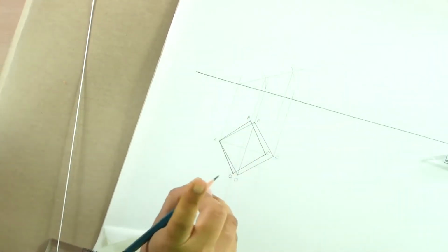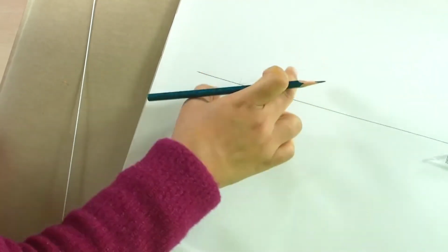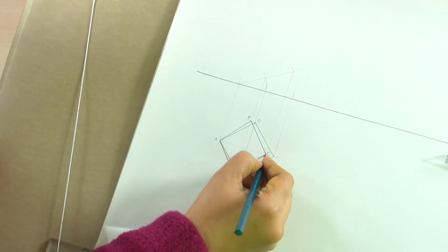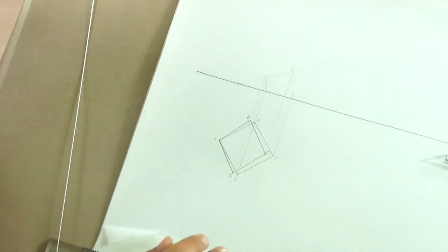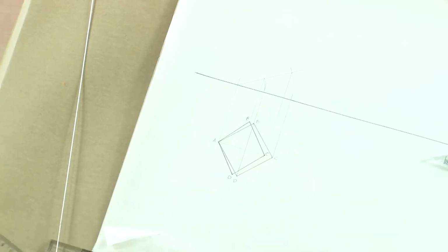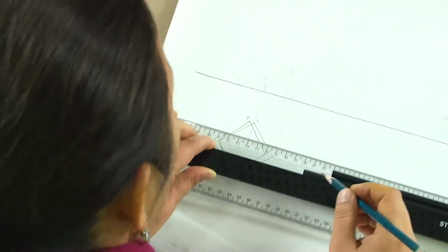So, this is the second shape, which is a slightly deformed square, the new ABCD. In this case, what we have seen is that this diagonal AC is still seen in true length, and that is what we are getting here. So, this is the reduced shape. Now, this AC is going to make an angle of 30 degrees with VP. So, what do we take here? I am just drawing the horizontal projection.